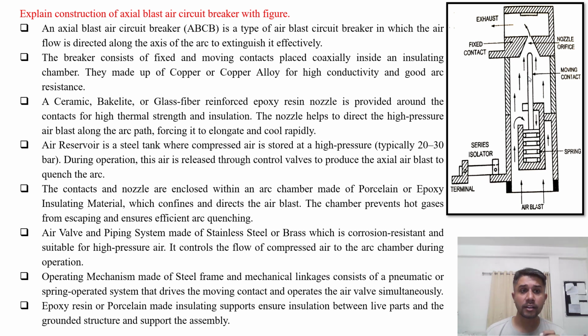A ceramic, bakelite or glass fiber reinforced epoxy resin nozzle is provided here. This is the nozzle, around the contacts for high thermal strength and insulation purposes. See, this is the orifice of the nozzle and this is the nozzle. You can visualize this. Now, the nozzle helps to direct the high pressure air blast along the arc path, forcing it to elongate and